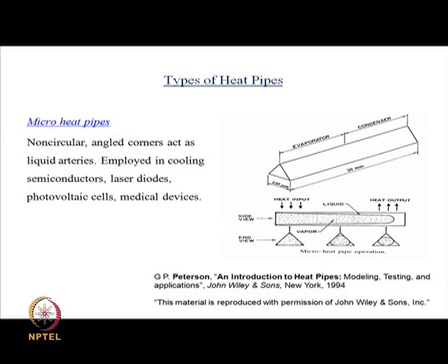So, at the cold side, what you would expect is that the liquid is going to fill almost all the corners of it. So, there will be liquid at the corners when we come towards the cold region, whereas if I come towards the hot region, the liquid will be depressed far towards the apex of the corners. So, towards the cold side, I have liquid everywhere. On the hot side, I may have traces of liquid left only at the very deep recess of the apex.